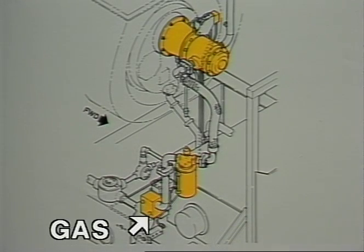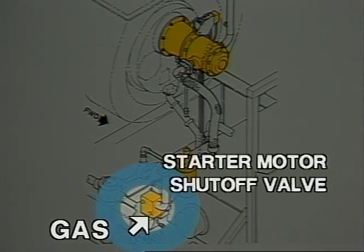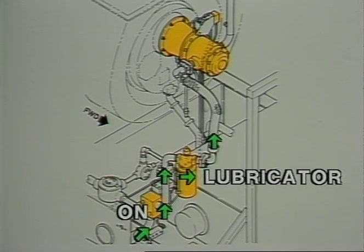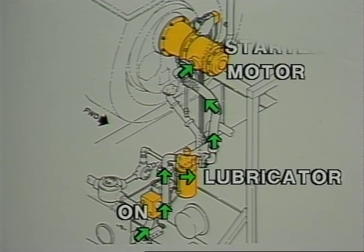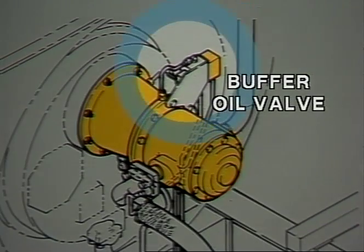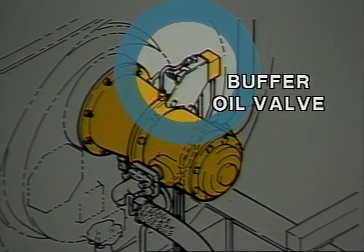As the gas enters the package, it first encounters the starter motor shutoff valve. This valve simply functions to turn the gas supply off or on. With the valve in the on or open position, the gas will travel through the lubricator to pick up a fine oil mist and then enter the pneumatic starter motor to begin rotation. The buffer oil valve mounted here is used to prevent starter motor gas from entering the accessory drive area.